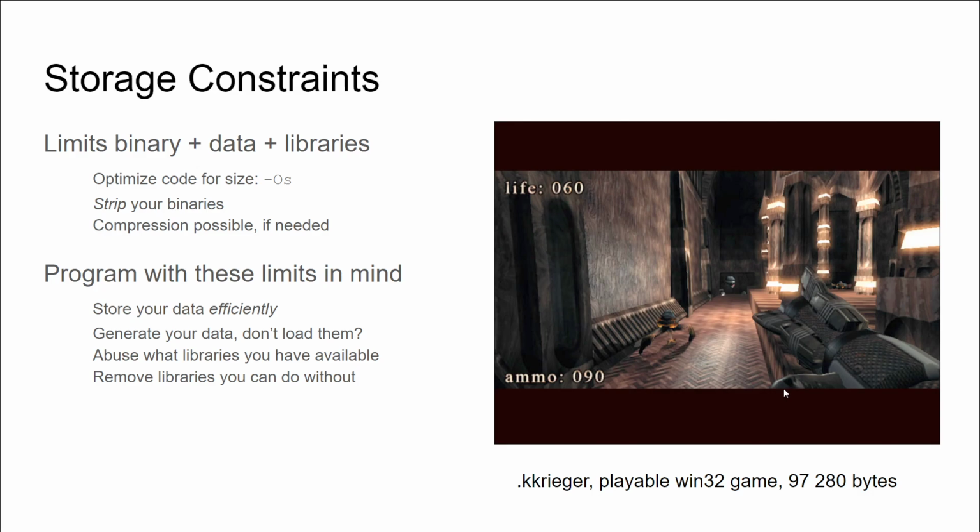And getting around the constraints that your output code needs to fit into this small little ROM chip is a challenge at times. You can tell your compiler to help you out by optimizing your code for size. That's the -Os flag.